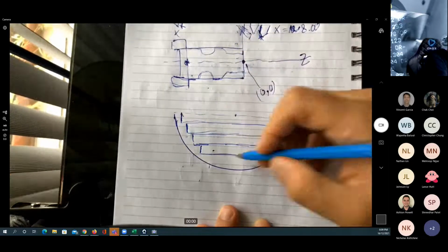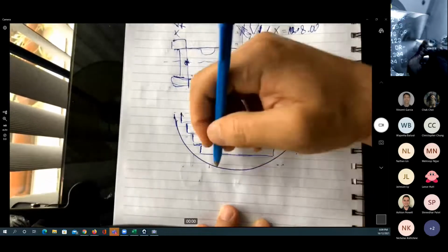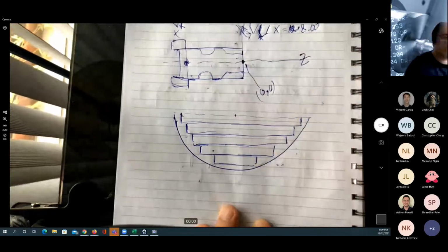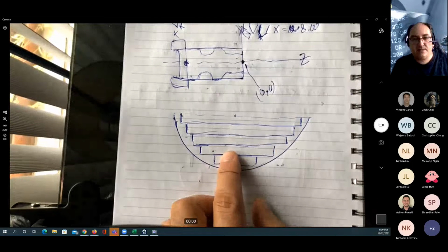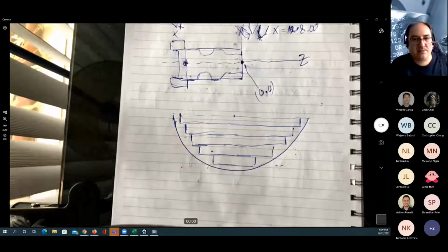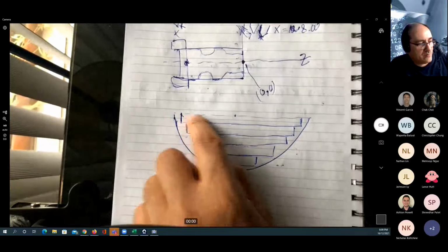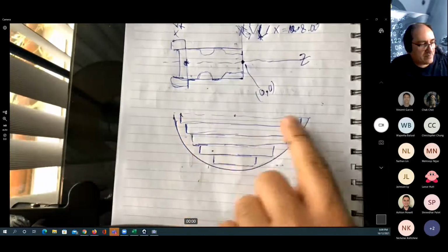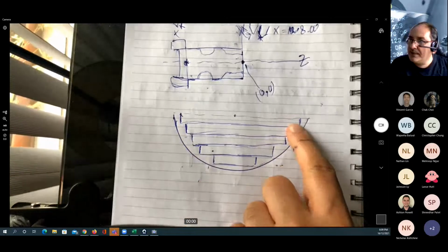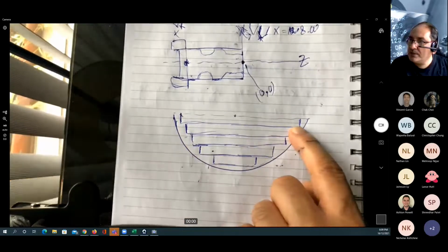Fourth. And the fifth. Well, I consider this one as fifth, but we can even make it less or more, depending on the radius we're going to have and the material we're going to cut. So I can decide what will be the depth of the cut. So we remove this layer first, moving from here. Okay, we set the depth of the cut to this point.